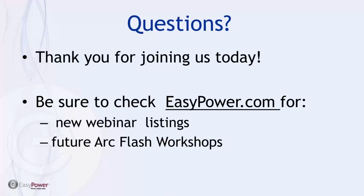So if you remove or add breakers or an entire branch within your base case, that will be reflected in the scenario, because you're going through those macro changes to that scenario. For example, if you had a utility and deleted it from the base case, then went into the scenario you created before, you would get an error message saying this no longer exists in this scenario.